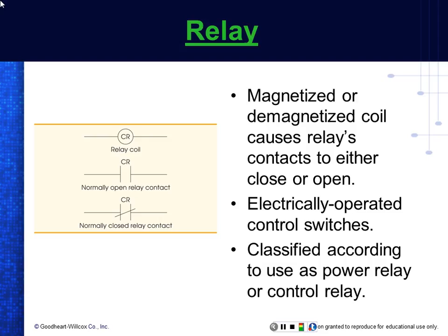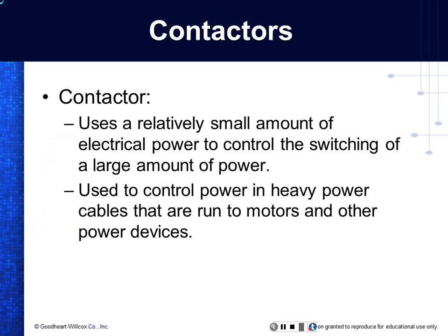In relay logic, we use those to turn things on and off. In PLCs, we don't have to. The PLC has those internal. So we can use as many of those as we want to. So that is one thing that motor controls you need to know. We don't have to have a physical relay.